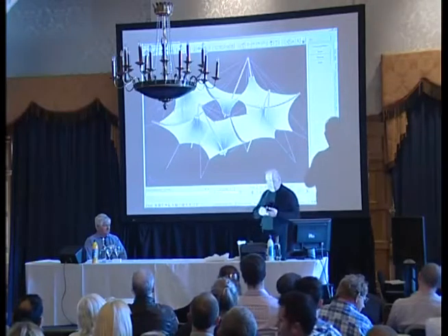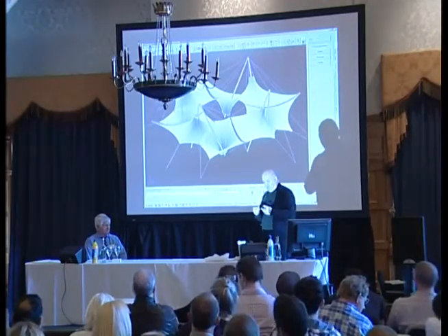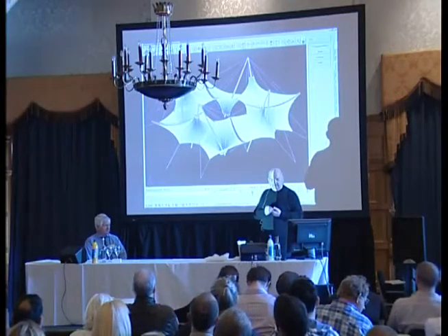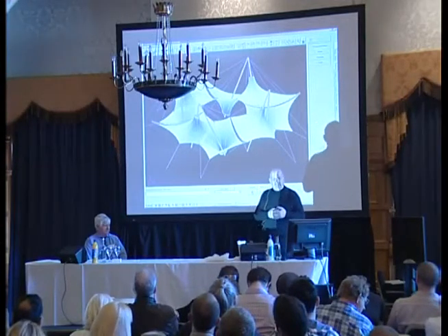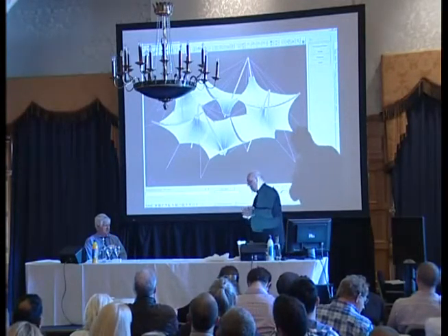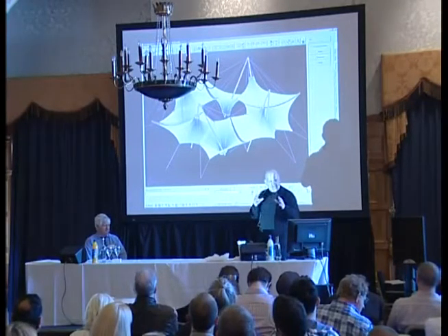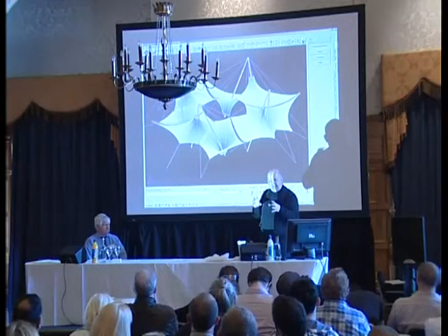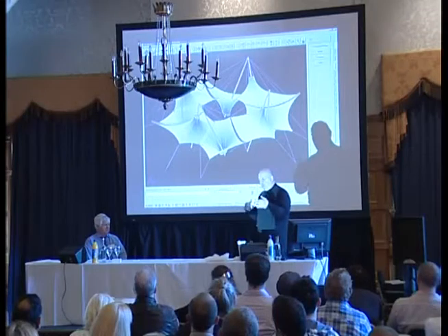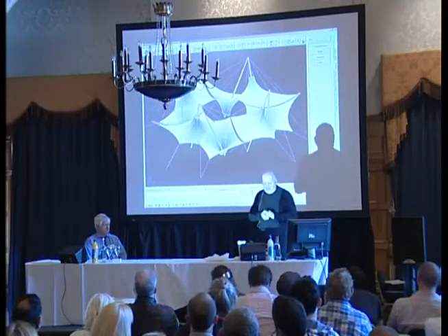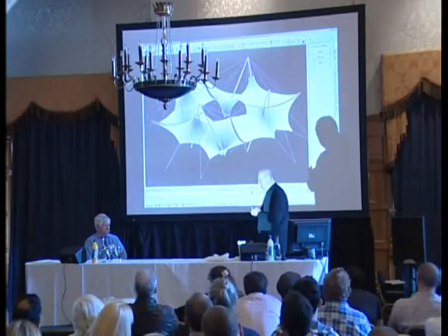So we've come to 3 conclusions here. That thin materials can perform really well if they're used in the correct configuration, i.e. use the shape to control any loads. That slender thin-wall members can be used if inspected and maintained correctly. We were talking about that before with the trusses and the aluminium. Nothing wrong with thin-wall tubes, but you must inspect and maintain them because thin-wall tubes are more susceptible to folding. And that tension fabric is a good structural material if edge stiffening and point load details are adequate.